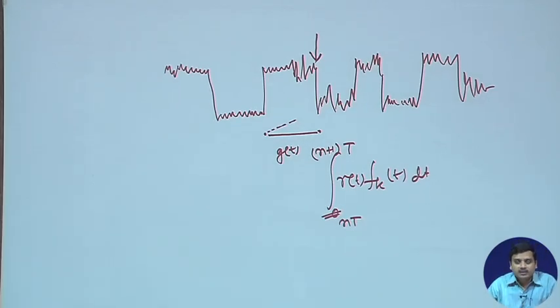So, that means, at the receiver we must have a clock which generates at a frequency 1 upon T. That means, it produces the clock at every T interval of time without fail. If you take real systems and real clocks, there are jitters in the clock, as well as, since it is an output of the oscillator, it is not necessary to produce the same frequency continuously. It will oscillate around some center frequency, and you describe such behaviors through a power spectral density of the oscillators. What it means is that it does not continuously generate the time T.